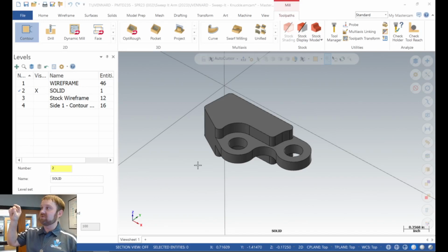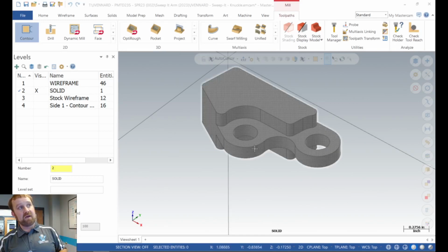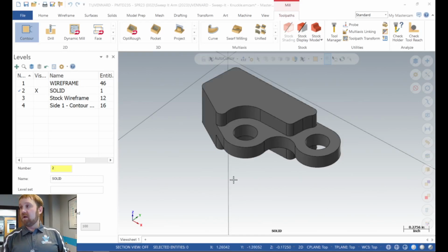I first decide how much of this I want to hold on to on the back side. Well, I know I can't hold on to any more than what this step is down here, because I've got to be able to machine that. Most of the time, my go-to is anywhere from 125 thou, depending on how much I've got to hold of the part. If I can hold on to a lot of the part, I don't need a real deep pocket to clamp on it. Or if I don't have a whole lot that I'm holding on to, I might have to cut my pocket a little deeper. This part, since that step's there, and I really want to make sure that I'm getting a hold of this geometry here, I'm going to just basically do half the part, which is a 1/4 inch deep.